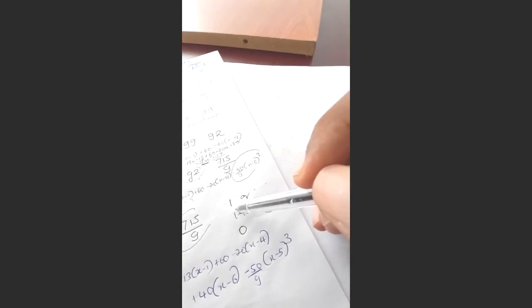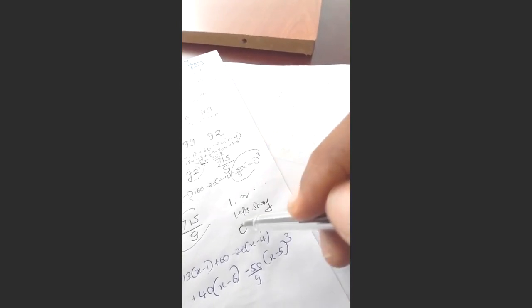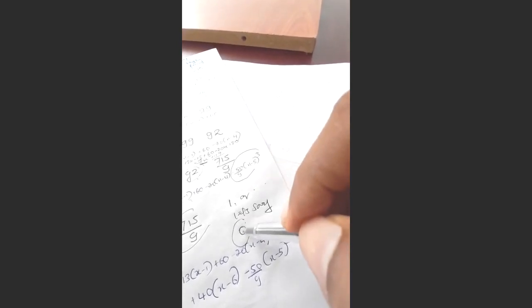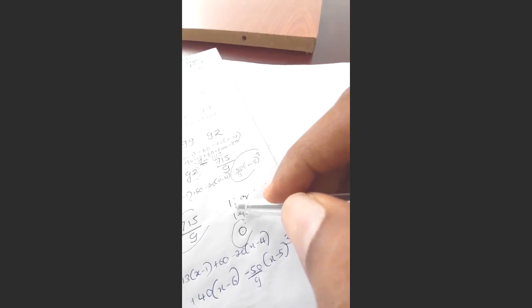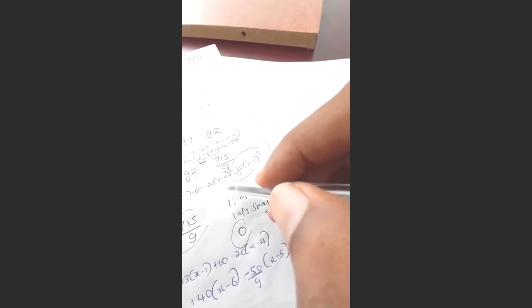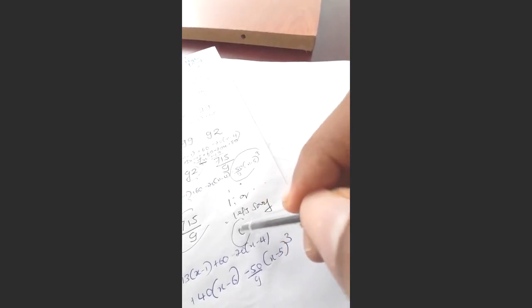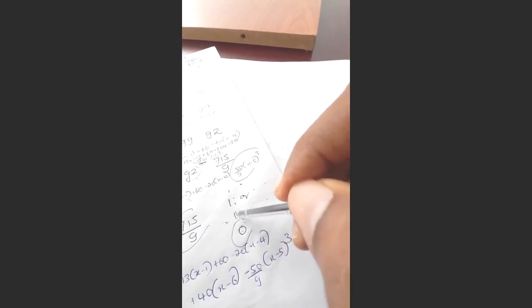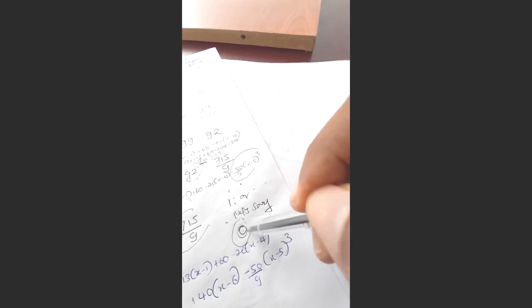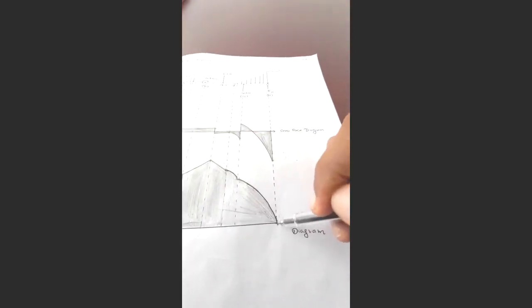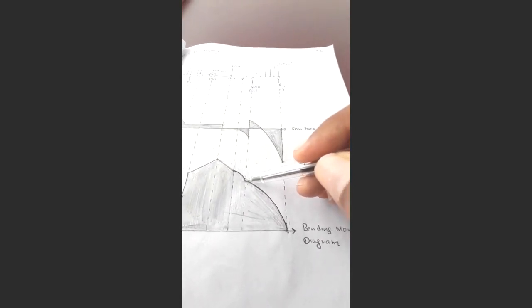Now the higher limit bending moment: when considering the calculations, it is 1, but theoretically it must be 0, right? I'm not saying 1 equals 0, but this is because of the decimal error. I told you the reaction that we have considered, 73 kilonewton, is not the exact one. I have explained that in the previous part. So it doesn't matter, you can even keep it as 1, but the better way is to keep it as 0, because the bending moment at this point must be 0. So the lower limit value is 715 divided by 9 here, and here 0 kilonewton meter.